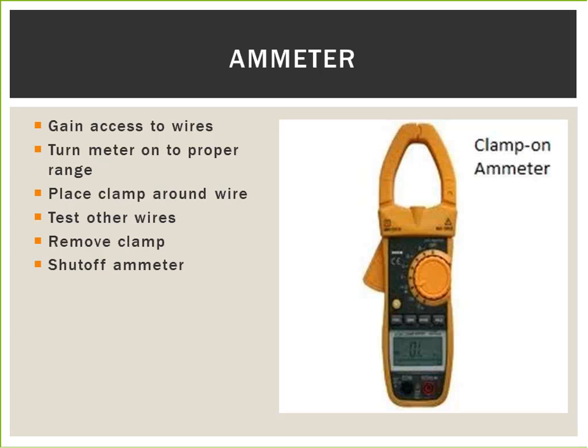Test the other wires that are feeding the device if there are multiple feed wires, such as a 220 volt AC 2-wire or a 3-phase 3-wire power circuit. All of the power wires, if multiple feeds are used, should be close in the amperage reading to each other.